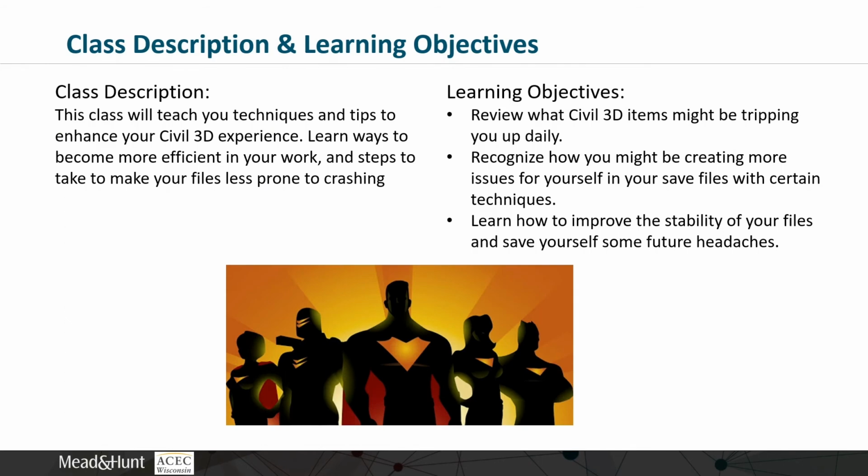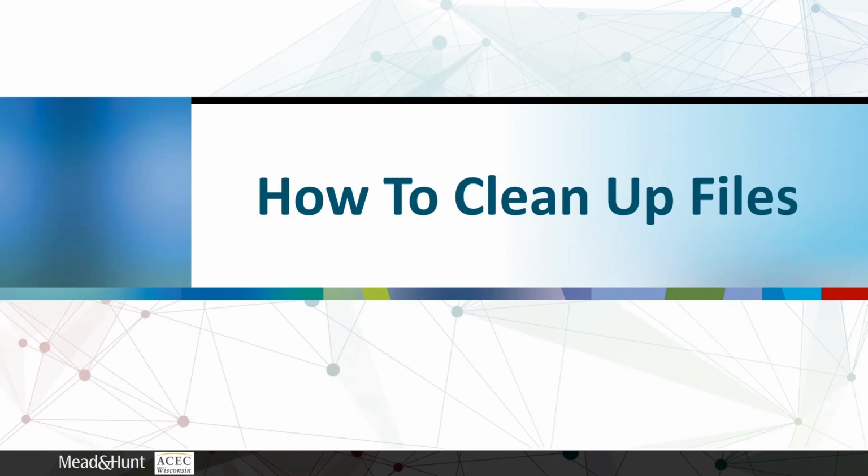This class will teach you techniques and tips to enhance your Civil 3D experience. Learn ways to become more efficient in your work and steps to make your files less prone to crashing. We're going to review what Civil 3D items might be tripping you up daily. We're going to recognize how you might be creating more issues for yourself in your save files with certain techniques, and we're going to learn how to improve the stability of your files and save yourself from some future headaches. Let's start with how to clean up files.